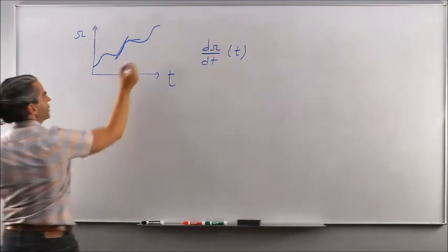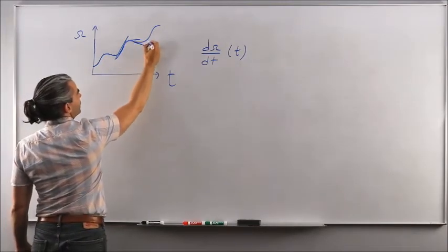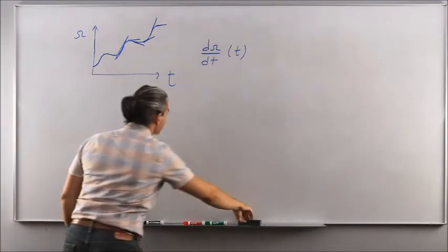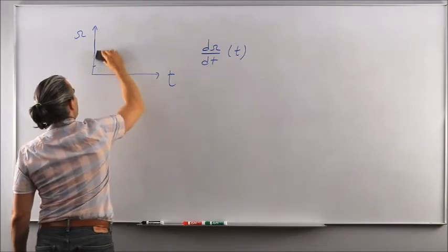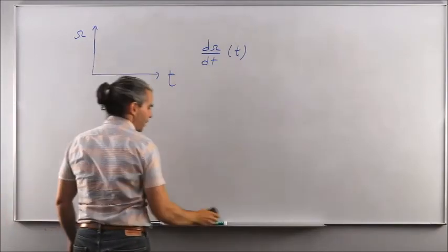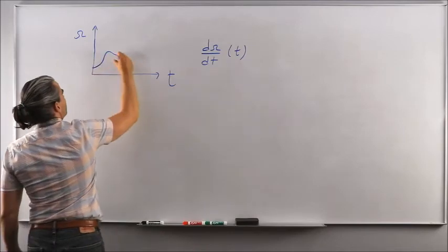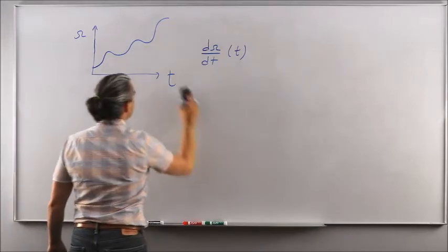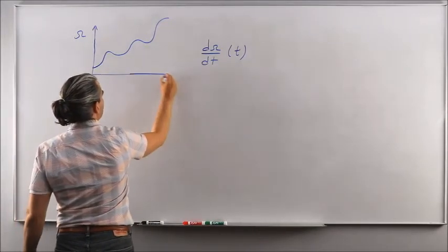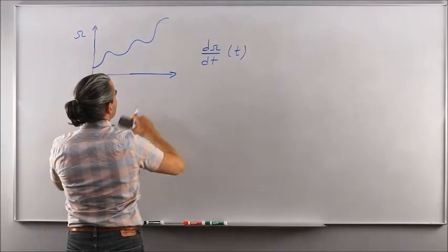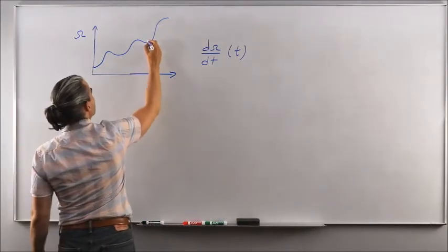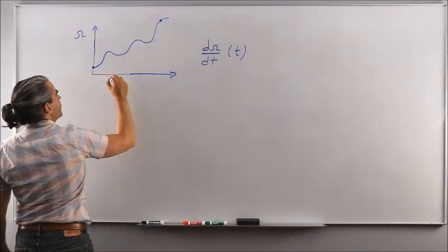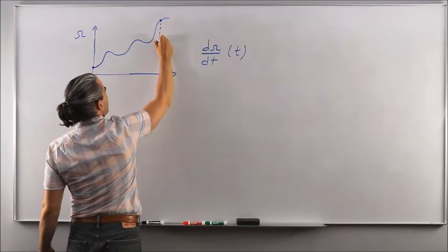Okay? And at some other time, the rate of change could be negative, positive, much more positive, almost zero, and so on and so on. Okay? So the output of your Gauss Variational equation will vary with time. Well, what is very useful to calculate is what's known as the secular variation. And that is the net change in your orbital element that you're looking at, calculated over one orbital period exactly.